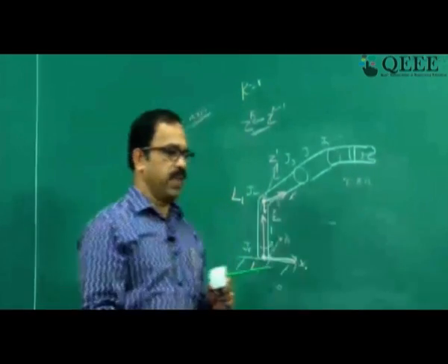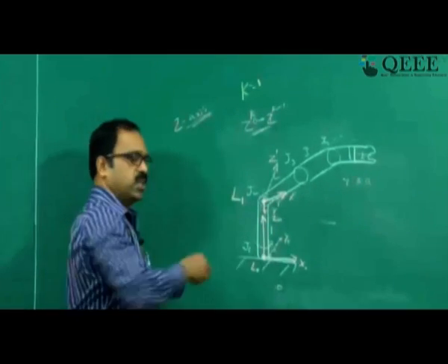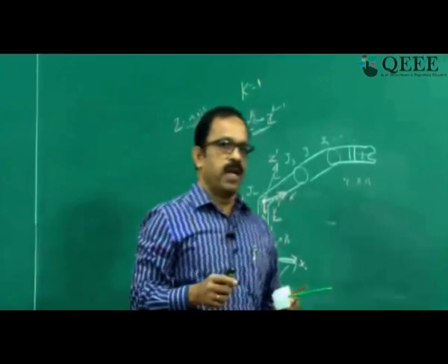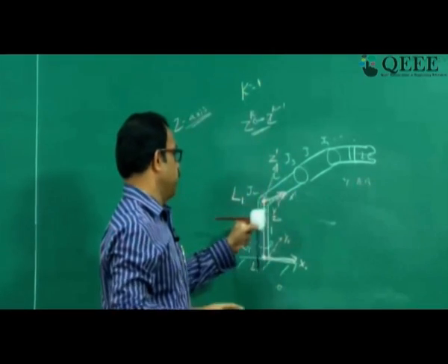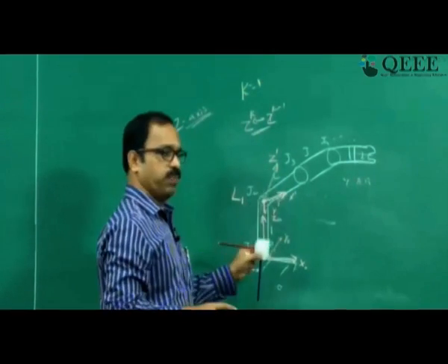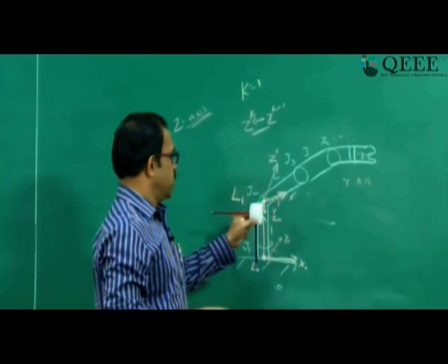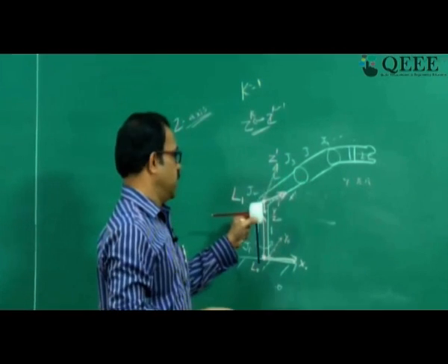So you look at the Z axis, then locate the origin Lk at the intersection of Z1 and Z0, and if they do not intersect, take the common normal, otherwise you take the intersection.